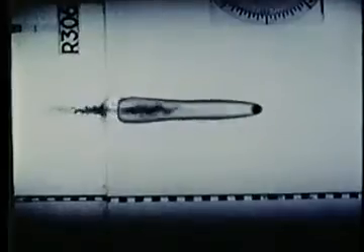Another type of cavity flow occurs when a missile enters water at high speed. In this sequence, a steel ball is shot into a tank of water. Here, the camera is turned so that the water surface appears to be vertical and the missile to travel horizontally. The cavity follows the missile into the water and eventually closes off, producing reentrant jets which are seen here in slow motion. Initially, the gas within the cavity attached to the missile is air rather than vapor. Progressively, the air is left behind, and if the motion persists long enough, the cavity content will be vapor primarily.